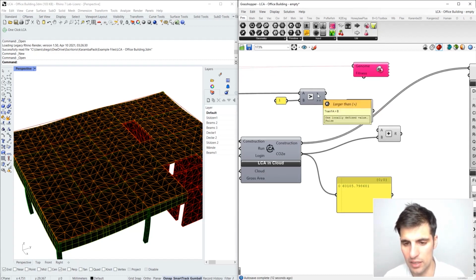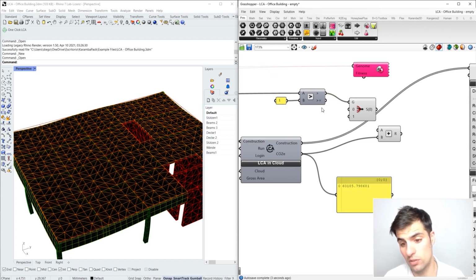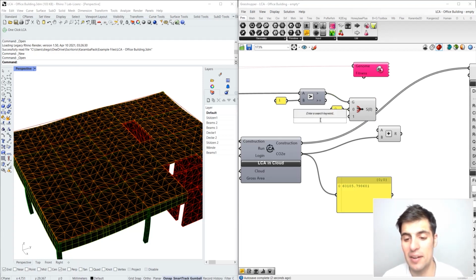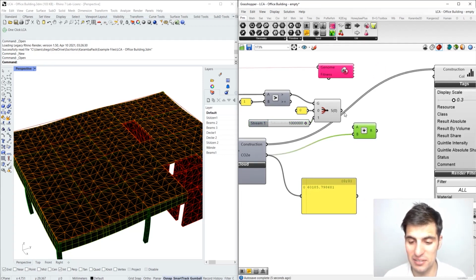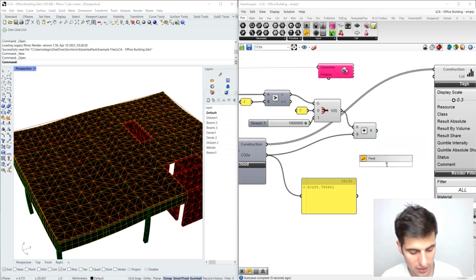If this is false, if the deformations are more or less okay, this is going to be 0. And if the deformations are very big, let's get a value, for instance, 1 million, so that Galapagos in this optimization loop sees that these solutions are not valid. That should be it, and this is my fitness function actually.